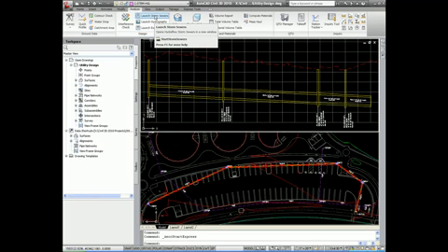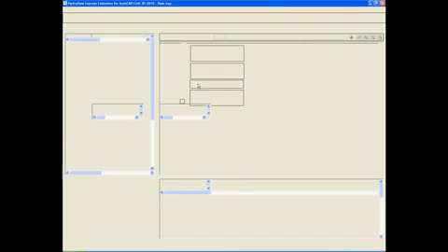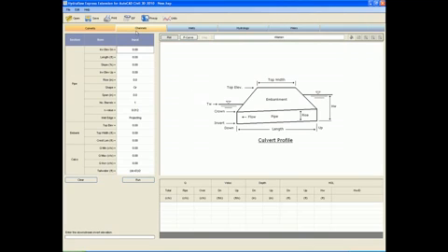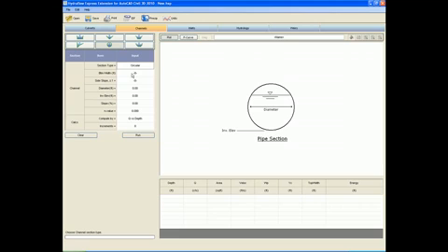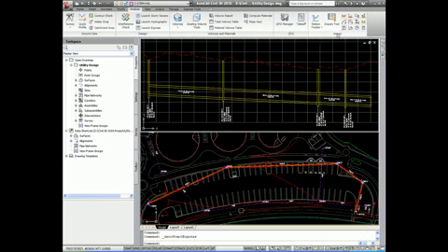The storm sewers program is for analysis and design of your storm sewer networks. Hydrographs is for modeling of watersheds and designing of ponds. And the Express extension is a really nice utility for doing some calculations, open channel flow. For example, circular pipe, you can put in some parameters and calculate the velocity, the depth of flow, etc.